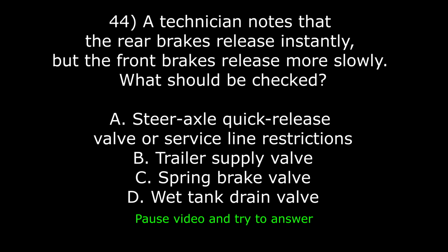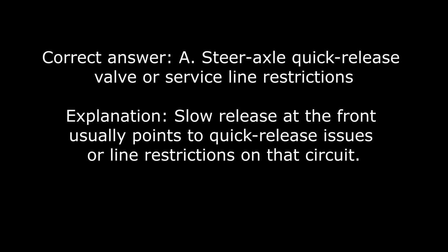44. A technician notes that the rear brakes release instantly, but the front brakes release more slowly. What should be checked? A. Steer axle quick release valve or service line restrictions. B. Trailer supply valve. C. Spring brake valve. D. Wet tank drain valve. Correct answer, A. Steer axle quick release valve or service line restrictions. Explanation: slow release at the front usually points to quick release issues or line restrictions on that circuit.